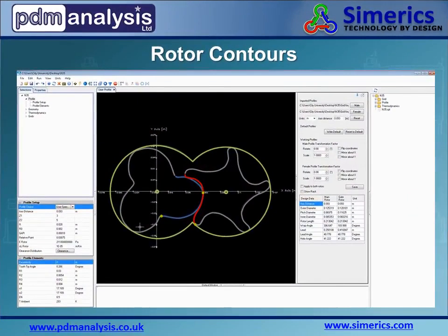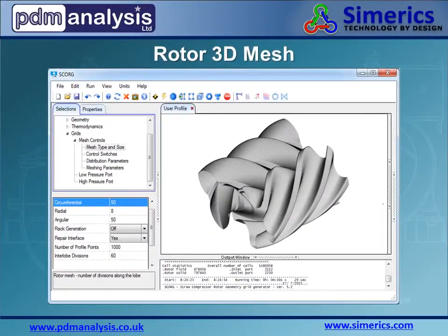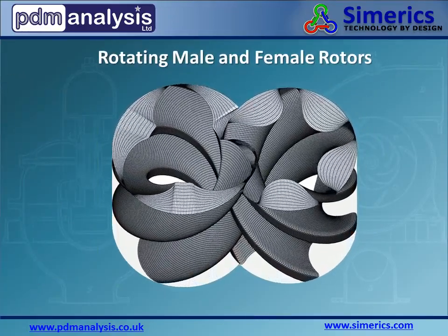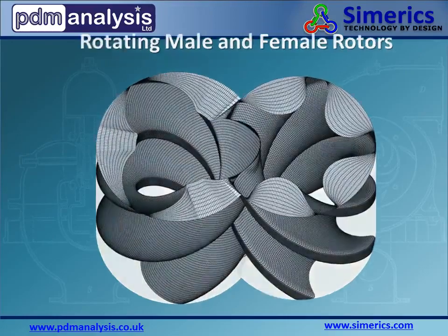Within SCORG, the imported rotors can be manipulated, scaled, and modified. From the modified contours, the complex three-dimensional rotor mesh is then generated. Building the rotating 3D mesh is one of the biggest simulation challenges for this type of machine.